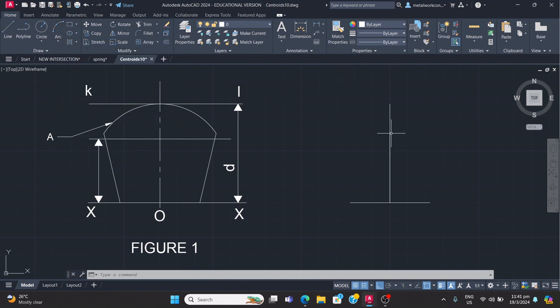But before I do that, I'm going to draw a line from the end of this point going to the left, enter, and right, which should be a construction line of any length that is long enough so that when you draw the arc, it can intersect it, okay? In a little while, you'll see what I'm saying.